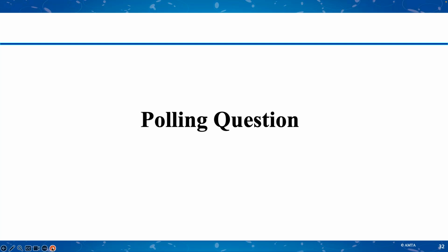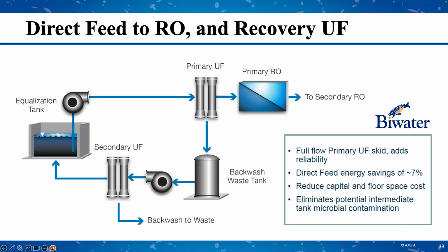I'll take back over the slides. Yeah, it's obviously a flow rate in the system is irrelevant as far as performance unless you know how much square footage of membrane is installed. So you can see how much flow is going through that proportion of surface area, and then you can track that line in the sand, that flow rate and performance, or TMPs and everything else. So same with RO and any other membrane application or filtration in general.